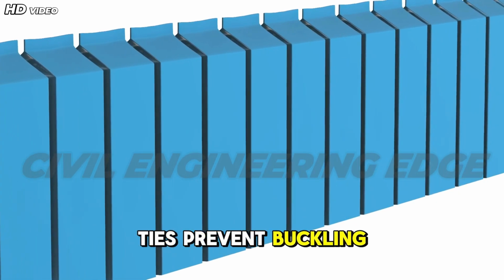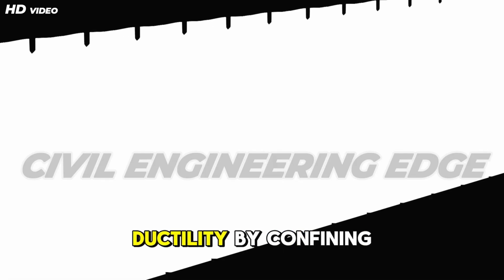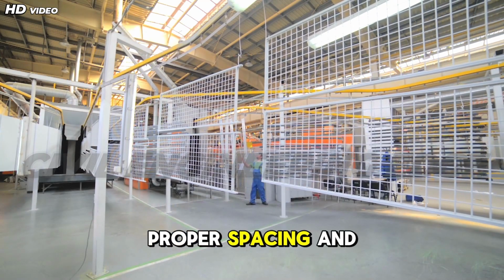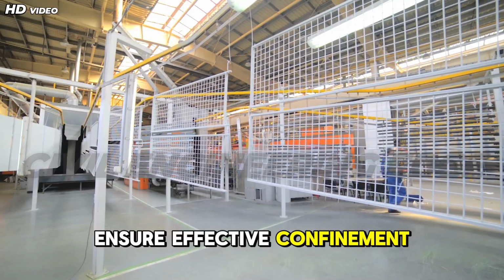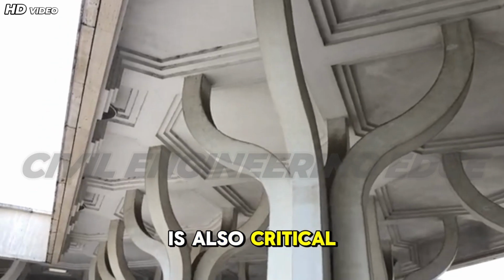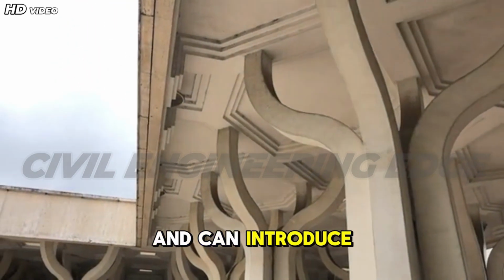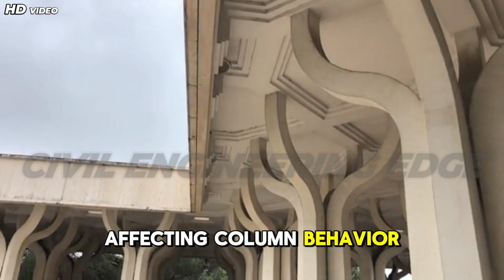Ties prevent buckling of longitudinal bars under compression and improve ductility by confining the concrete core. Proper spacing and secure fastening of ties ensure effective confinement, especially in seismic regions. Bar placement accuracy is also critical. Misaligned bars reduce effective cover and can introduce unintended eccentricity, affecting column behavior.